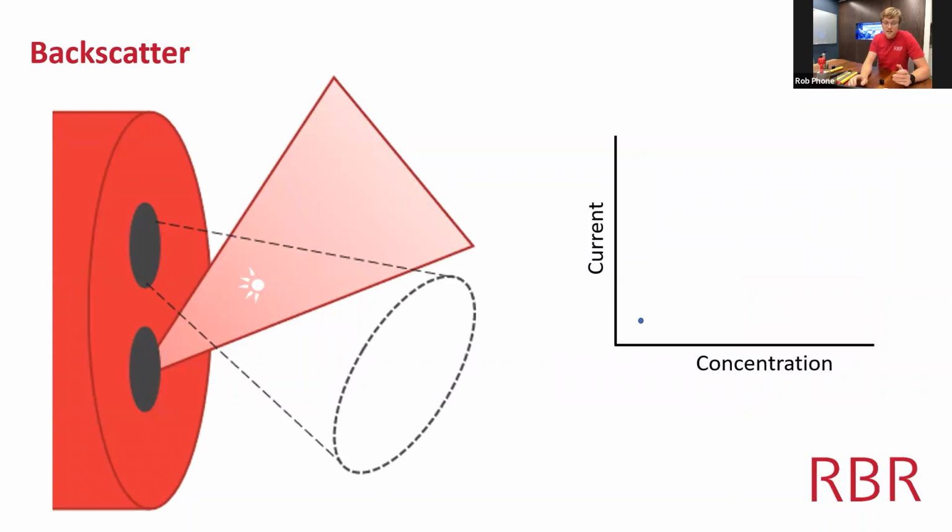So here's a depiction of what we end up measuring as particles in this sample volume increase. As the particle density increases in concentration, the current that we're getting back on the photodiode also increases in a linear fashion to a particular point. At some point, going the wrong direction, the current starts to deviate from this linear path, and this is a bit of a unique problem.